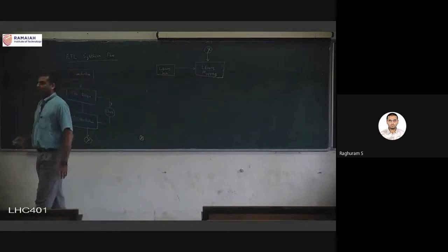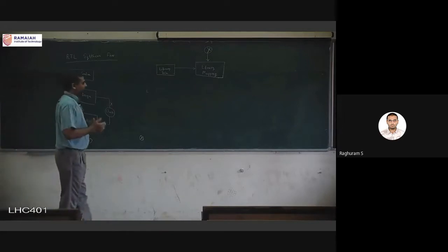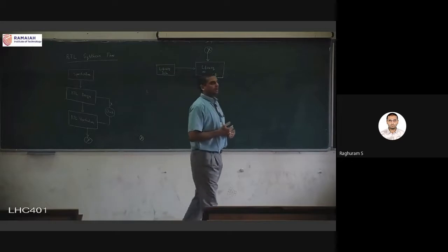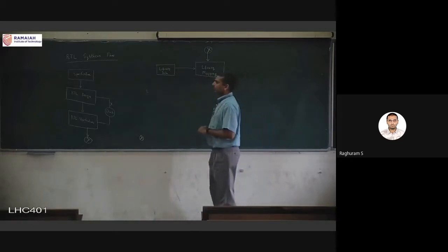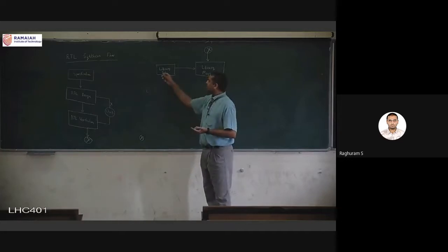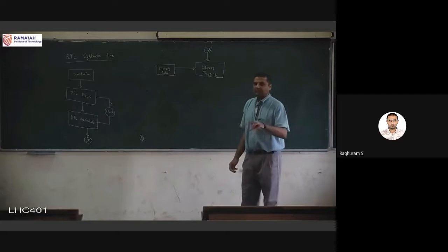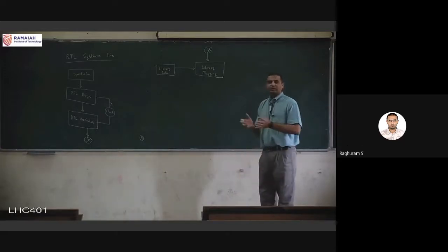the netlist is consisting of logic functions, that's fine, but not all logic functions are part of the library. Now, library is the keyword here. We have a finite set of gates for which we want to produce the final netlist.